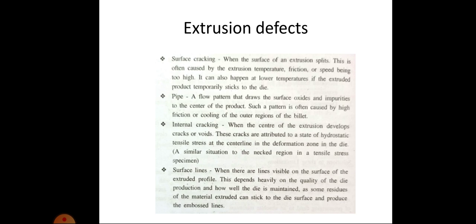Internal cracking: when the center of the extrusion develops cracks or voids, these internal cracks will occur. These cracks are attributed to a state of hydrostatic tensile stress at the center line in the deformation zone in the die. Fourth one is surface lines.